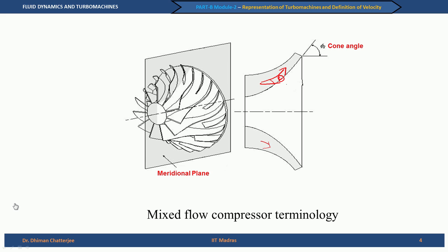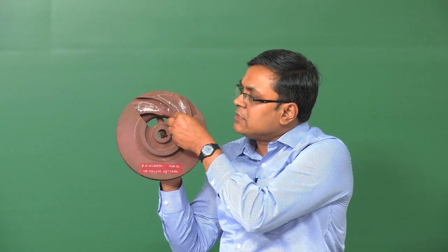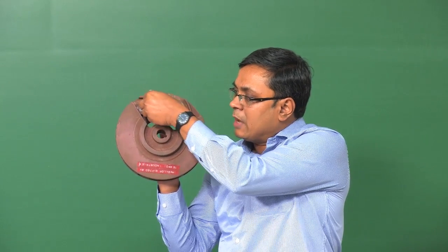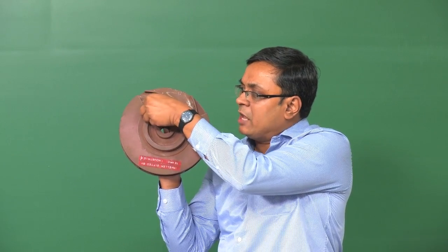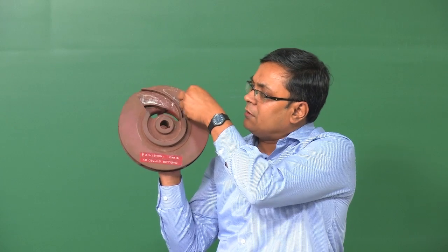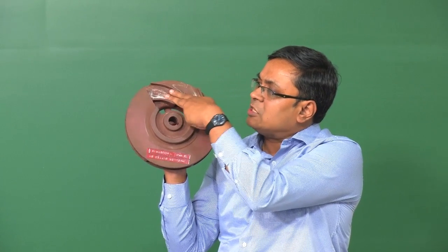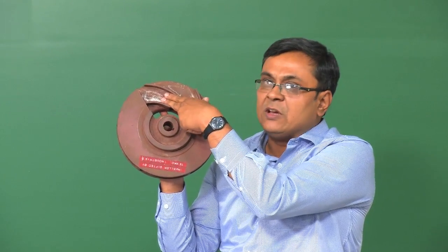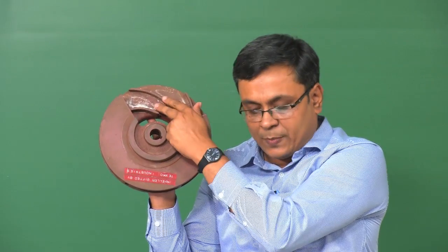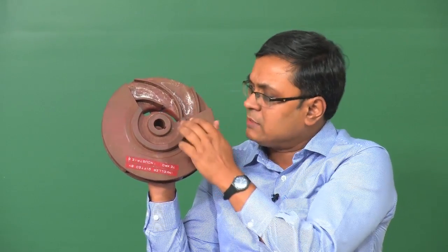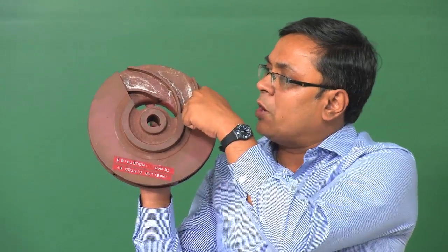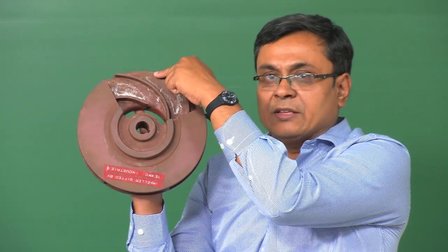So, let us look at a radial flow impeller very closely. This is the vane and this is the next or the neighboring vane, this is another vane, and this passage which shows my fingers inside between the two vanes is called the vane passage, and the flow in this case comes from the smaller radius to a larger radius.